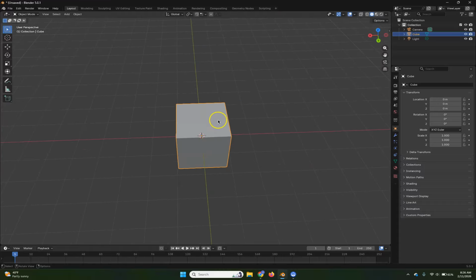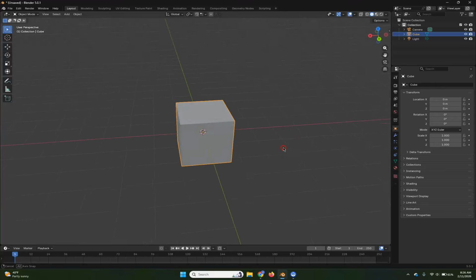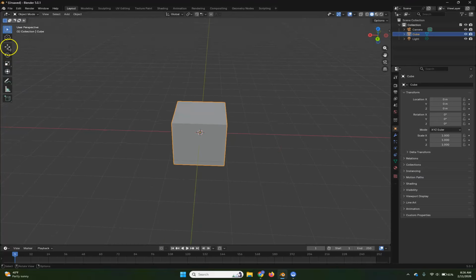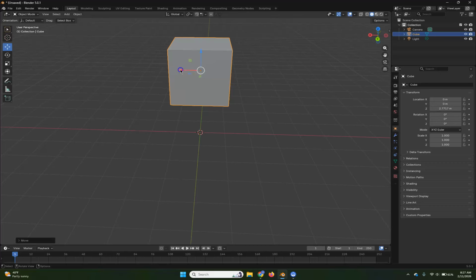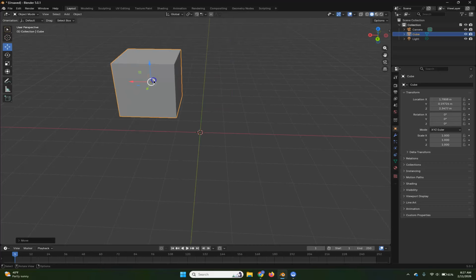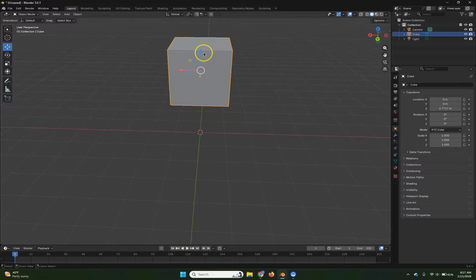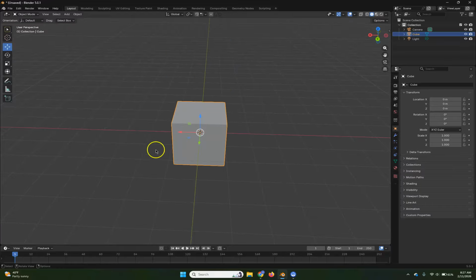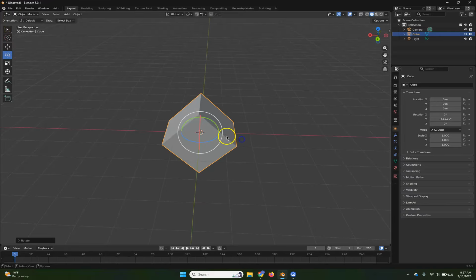So that's how you do that. Now, the next most basic thing is your transforms, meaning to move, rotate, and scale. You can do this two different ways. They added this over here, which you may appreciate if you have come from another app. You can go to move and it'll bring up this manipulator, and then you can grab based on the axes, or grab in the center. You always want to grab on axes to make sure you're snapping to an axis and not moving it in all the dimensions. Then there's rotate, and that's your typical rotate.